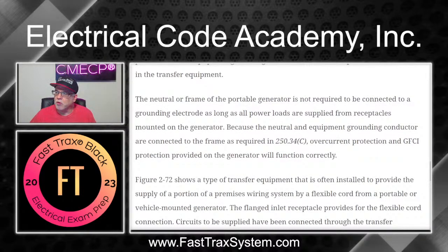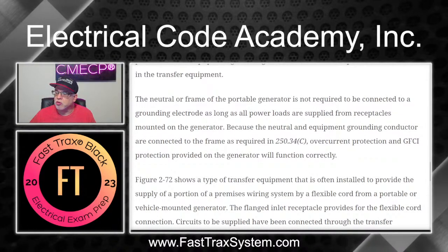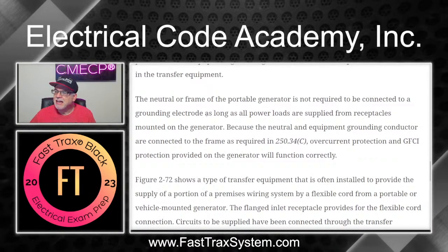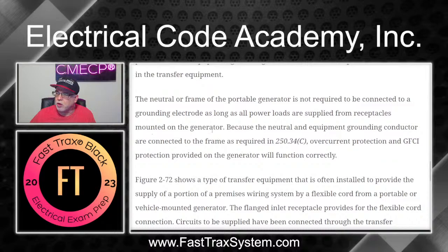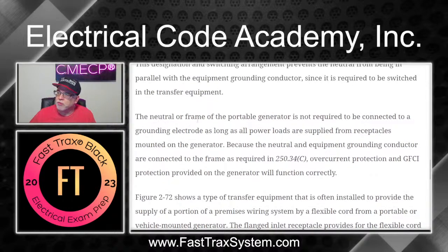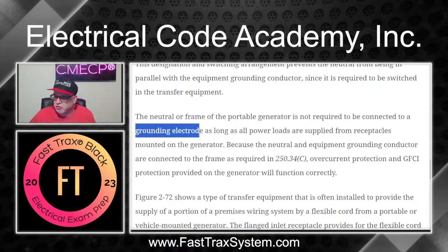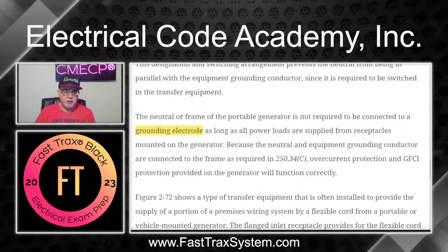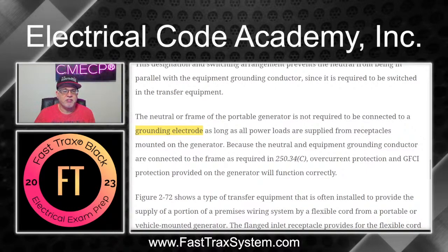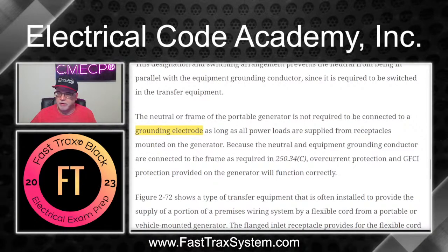It says the neutral or frame of the portable generator is not required to be connected to a grounding electrode, and we talked about this, as long as all power loads are supplied from receptacles mounted on the generator, okay? So the neutral or frame of a portable generator is not required to be connected to any electrode. We saw that. That was the very first thing that we looked at. Not required, if all the load is supplied through receptacles that are mounted on the generator, or the actual equipment associated with that generator is mounted on that actual generator, okay?